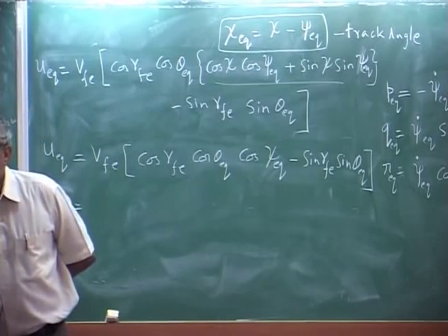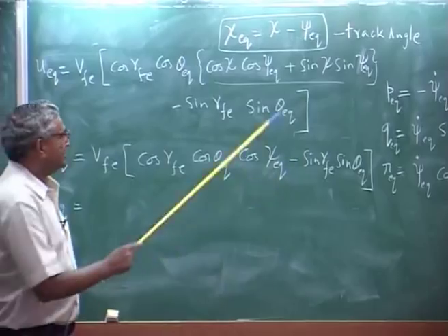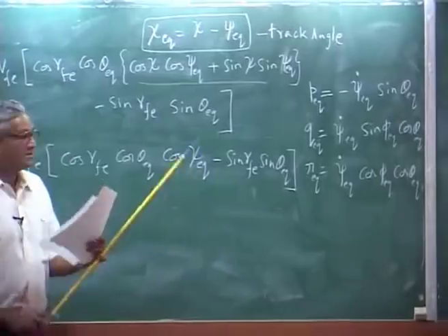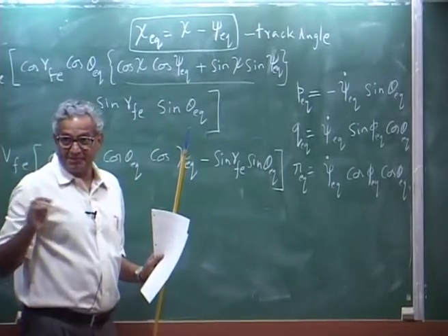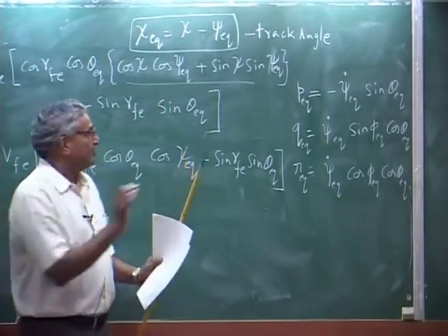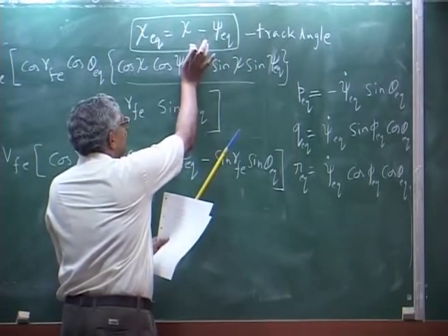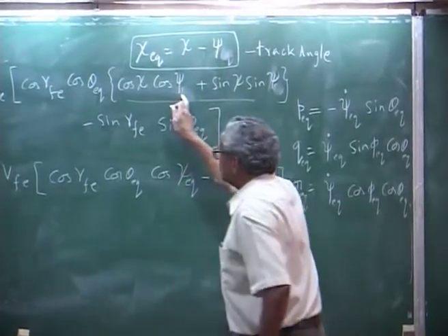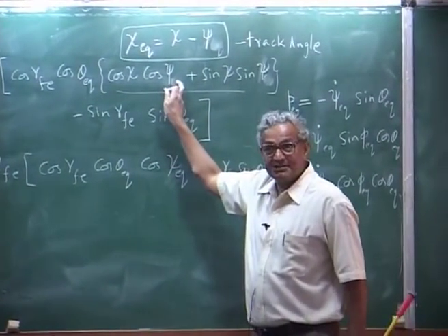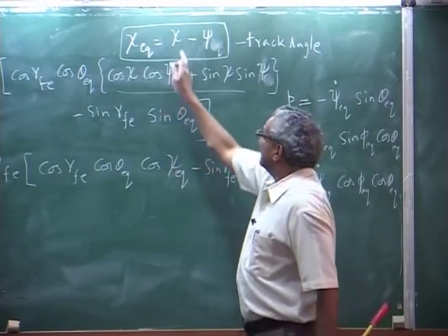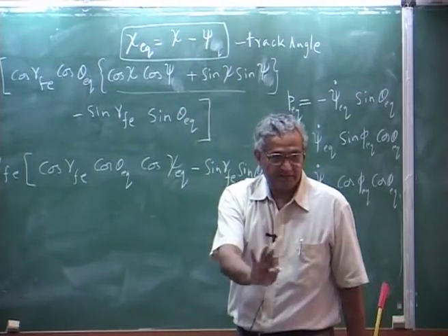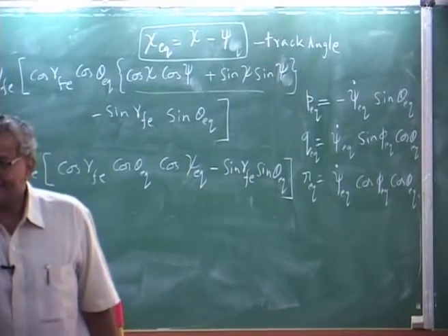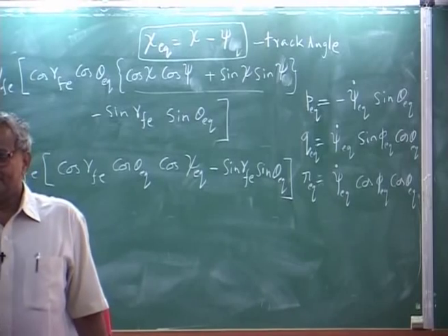It is also changing with time. So, I can't put a psi equilibrium, because you said psi dot has an equilibrium, that means psi cannot have an equilibrium because it is turning. So, usually what is done is you do not try to put an equilibrium here, you say these two quantities are varying with time, but their difference is a constant. Both of them are varying the same amount, the difference is a constant.